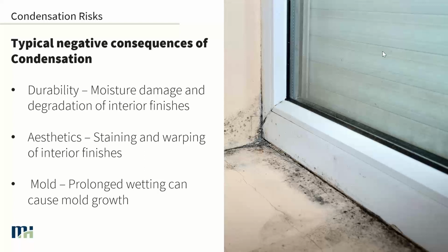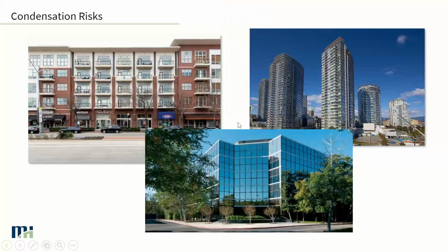And then if it's left too long, you get the potential for mold to grow, causing health issues. So these are the main items to watch out for when we're talking about condensation, and that's really been the focus for most of our buildings when we talk about condensation risks, whether it's low-rise residential, high-rise, or even office buildings.